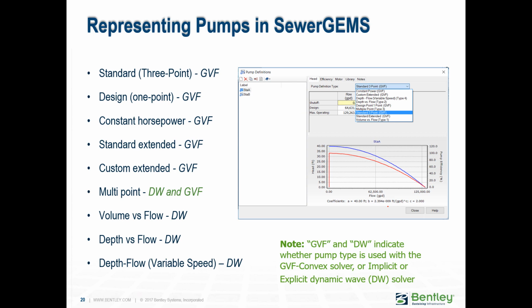All right, so now that we have a pretty good idea of pumps and what things we have to keep in mind, let's see how we model things in SewerCAD and SewerGEMS. There are different options, and when you double click on a pump, you see this called the pump definition, the place where we saw yesterday you input the pump curve.